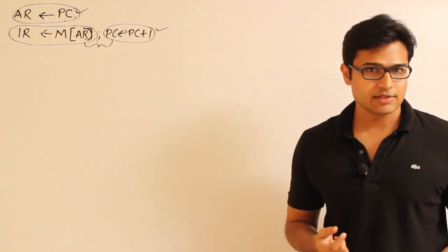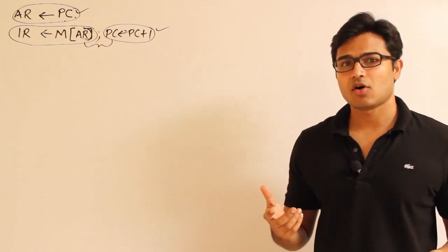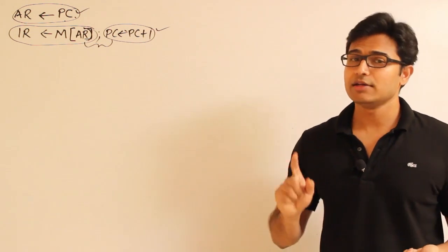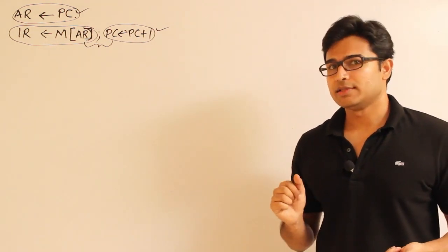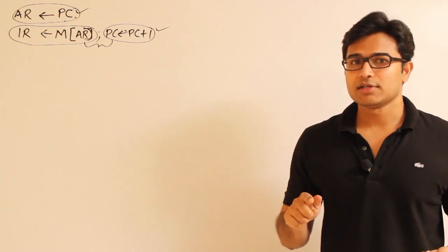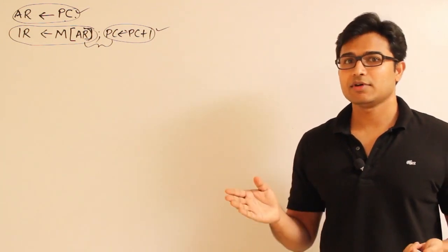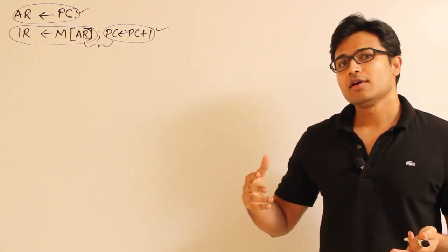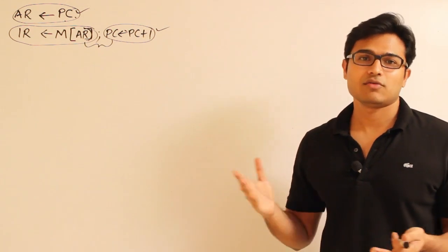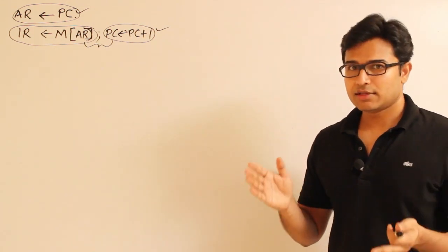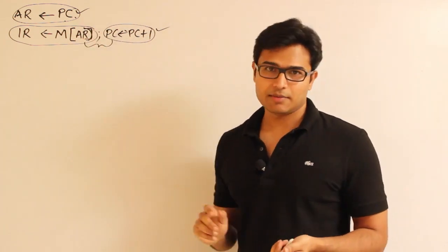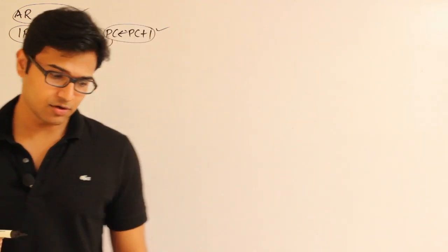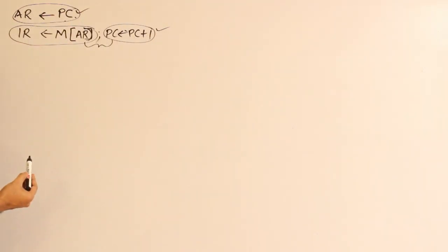See, we are going to have a system clock which is going to generate the clock signal, and that one will be given as input to all the devices. So all the devices are definitely going to see the clock pulses, but then they should distinguish one clock pulse from the next one, at least during the execution of an instruction. Once the instruction execution is over, for the next instruction they can again start from zero, but while executing an instruction, all these operations have to be timed. For that we need the timing logic. So how to generate this timing logic, watch it carefully.